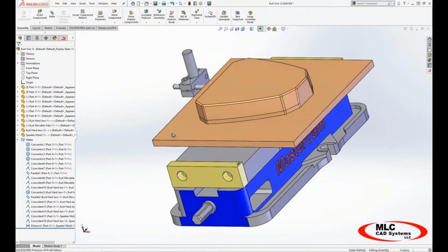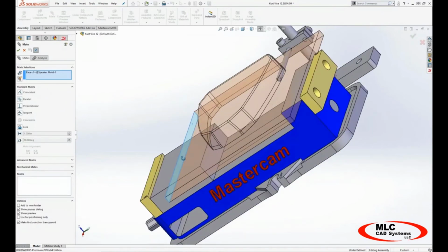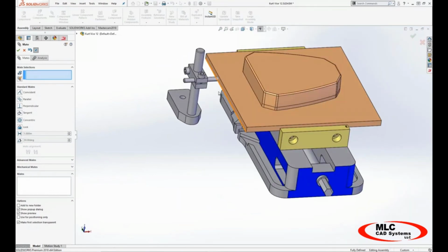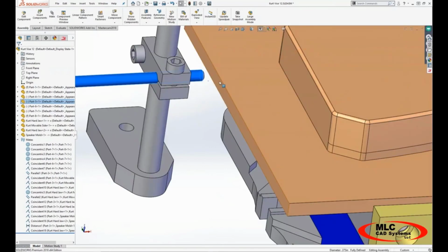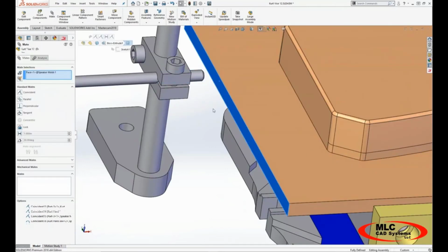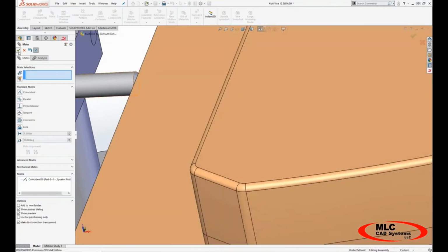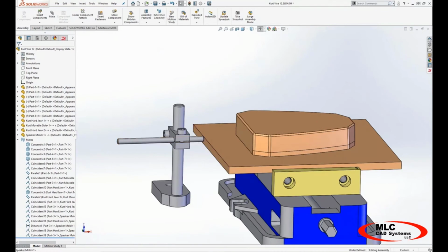The last part of this process, so actually I see a couple of things. We'll come in and bring this back, go ahead and close the vise so that it looks accurate on that. And maybe move this device over here to the left. This is what we refer to as a part stop, and it's just a little tool so that when the operator loads the part into the vise, he can repeatedly put it to the same position every time.